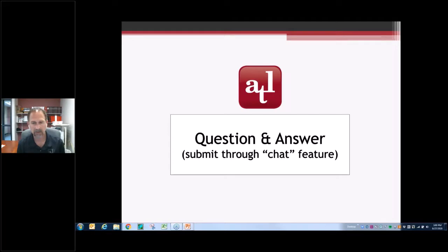But I would say for impulse response within the slab itself, not underneath the slab, you'd have to have some significant deterioration, like maybe tennis ball size. Anything smaller than that, and I'm not sure the impulse response would show much of a difference in that mobility.